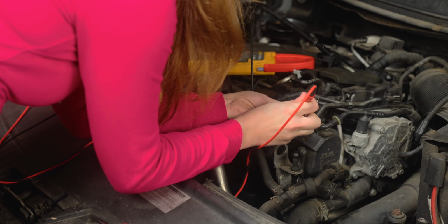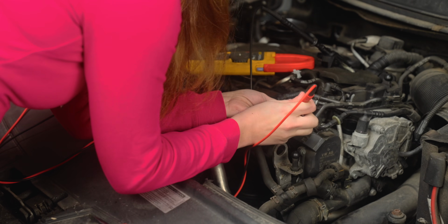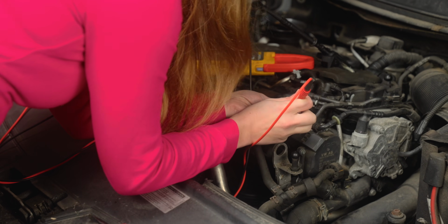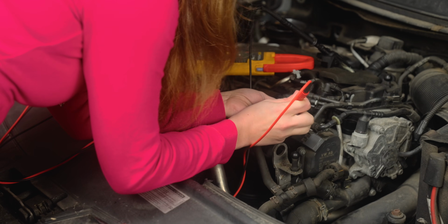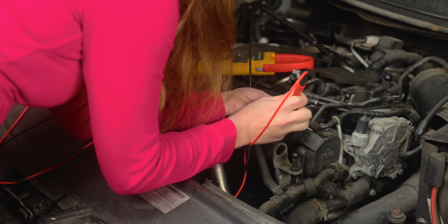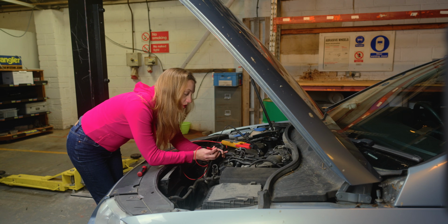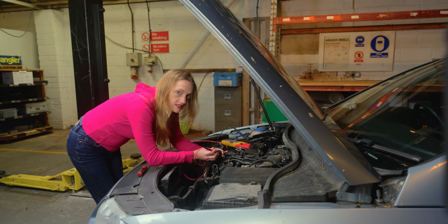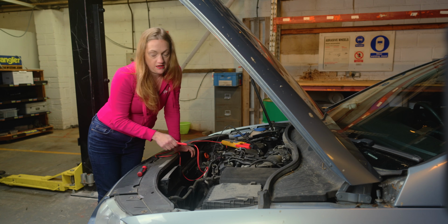We have 12 volts, 12 volts, nothing, 5 volts, and 5 volts. I've got 12 volt, nothing, 5 volt, which means I've got all the feeds I need. Now, this is a 5-wire plug. In a 5-wire plug, we have power and earth for the motor, 5 volt reference, a signal wire to command the movement, and then a feedback wire which tells the ECU where it's at.